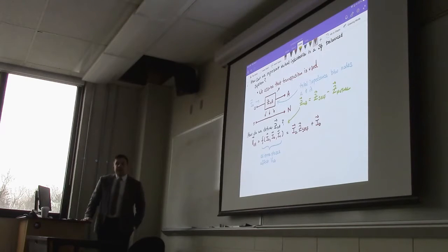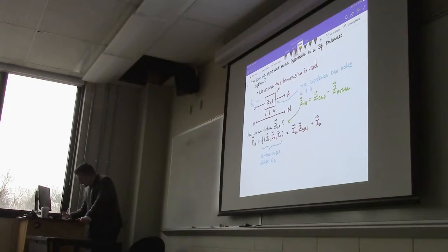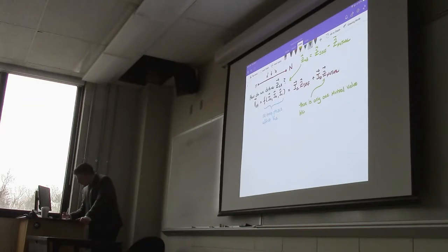So IB times the mutual impedance, which again for this expression, we are assuming there is only one mutual value because transposition is used and therefore